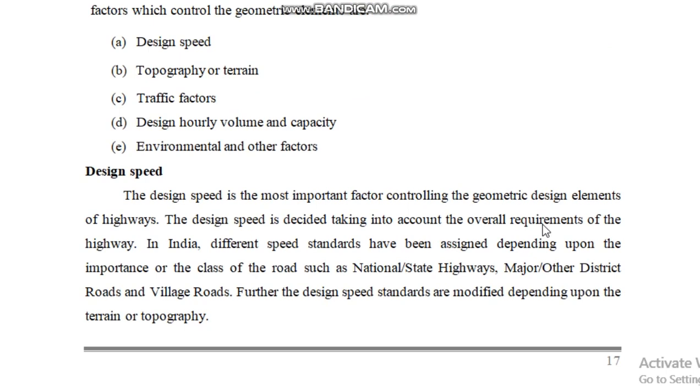So in such cases, all the geometric features that we are going to take will be at the maximum extent of safety. So very wide curves, and then wide carriageways, and supporting extra widening and proper super elevation, all these factors will definitely be influenced with the change in design speed.